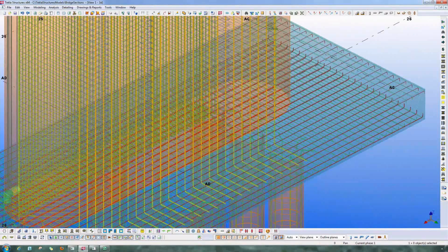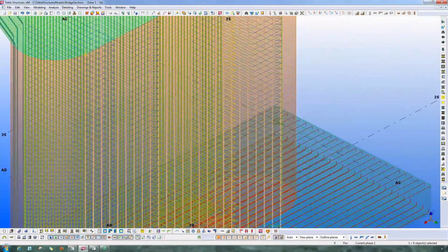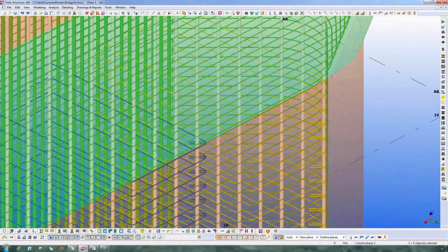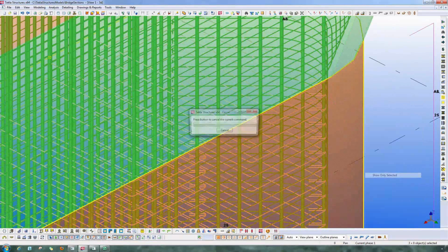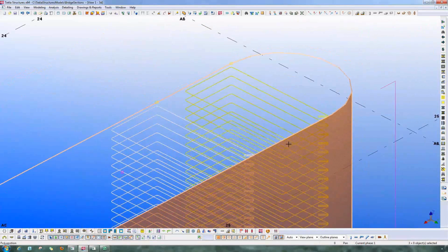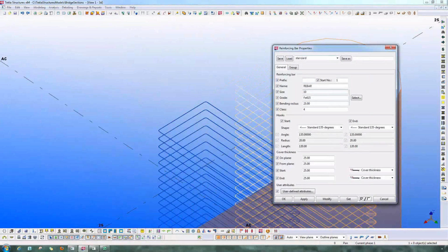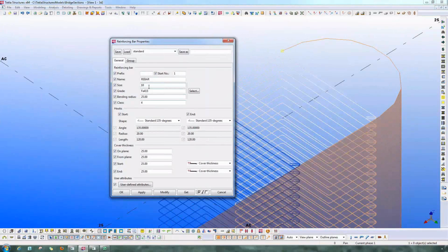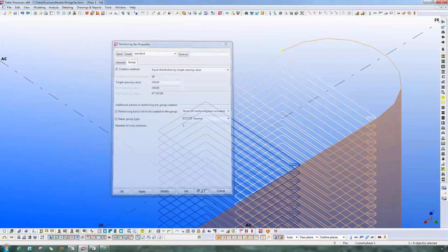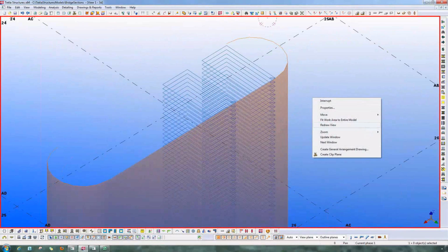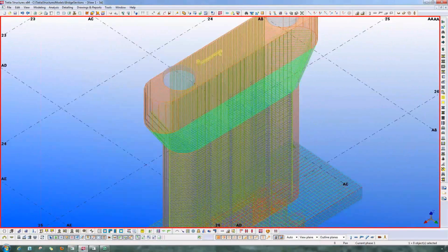So going inside the pile cap, here we have this stirrup information also. And this stirrup information, let me just select this stirrup and show only selected. So we can see only the stirrups with the pier here. And these are all intelligent. We can change the sizes and the hook details, and even the spacings for that rebar, that is possible. And even we can copy and paste in the other concrete part also very fast. So if I redraw, I have all the rebar information in it.